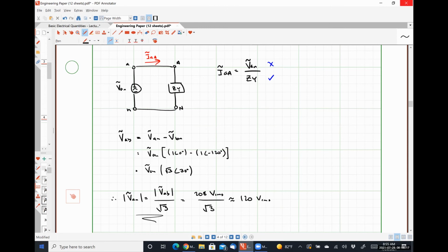The reason why I chose these numbers is this system would be what's called a 120Y/208 system, which is how electricity is distributed to Nethkin Hall. If you went and you opened up a breaker panel here in Nethkin or one across the street in Bogard, at the very top, it would have a plate that says 120Y/208.